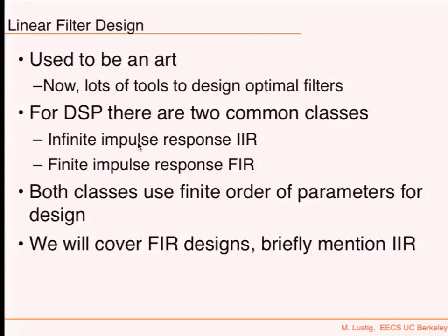Now, although IIR is an infinite impulse response, it does have finite degrees of freedom. So the parameters used to design the filters are of finite degrees of freedom. They're not arbitrary. Most IIR designs will be that way. I mean, that's how you pick them. For example, they have a certain number of poles that are allowed to be in the design, and so on and so forth. Though they'll have an infinite impulse response, it doesn't mean that there could be anything.